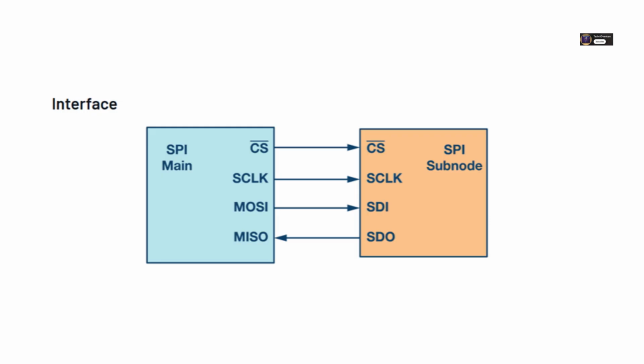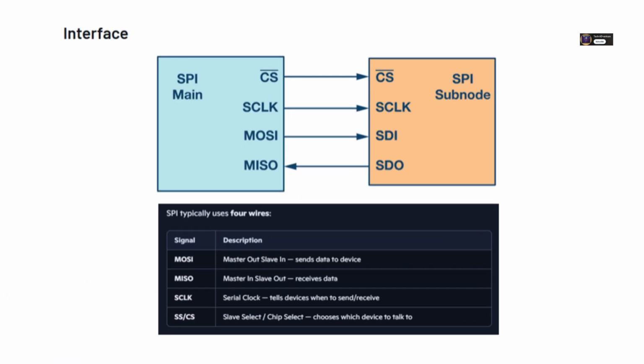What is SPI exactly? And why is it just so fundamental for anyone working with embedded systems? Okay, so SPI stands for Serial Peripheral Interface. And like the name says, it sends data serially. That just means bit by bit, one after the other, over specific wires. It started as a point-to-point thing, one master controller talking directly to one or more peripherals. Why it's so big in embedded? It really boils down to how directly and efficiently a microcontroller can chat with these other specialized chips using it.